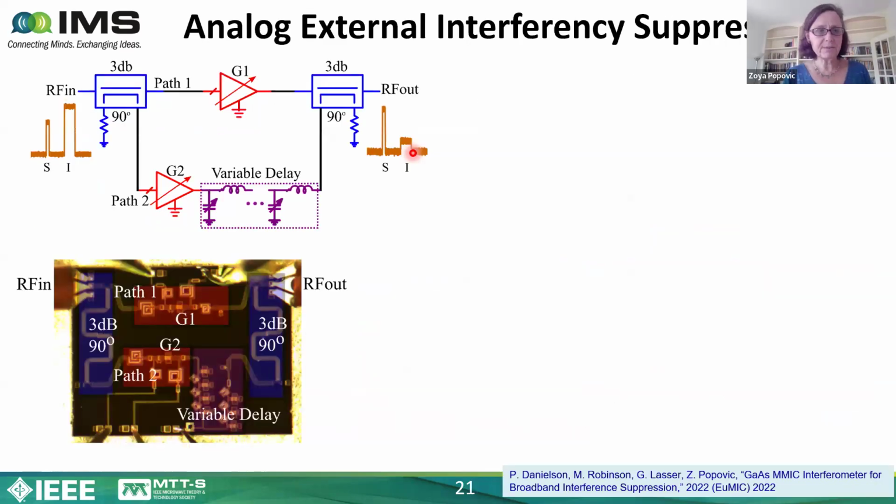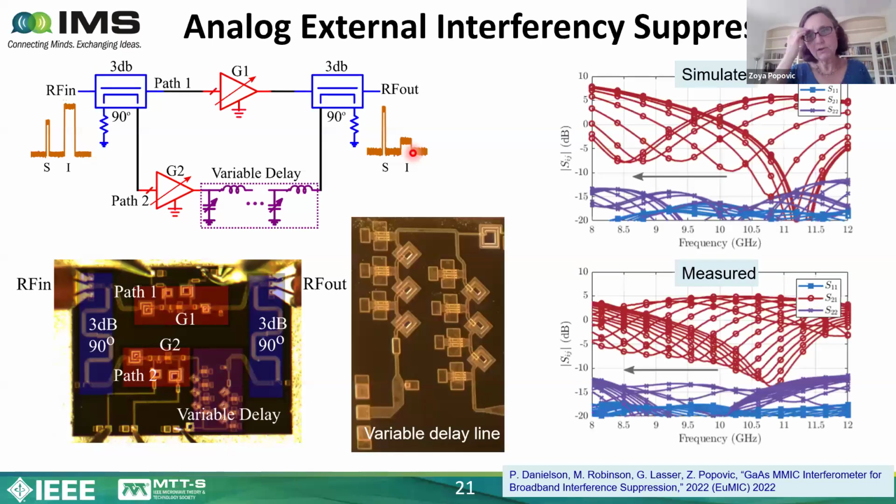If we're operating over a broad bandwidth, the analog thing you can do at the front end is to help the digital back end cancellation, interference cancellation, and that's for this external, other signals that are popping into your band. And what you do there is, for example, you can make an active notch. So basically an active filter that also has some gain, and you can notch out the frequency that is interfering.